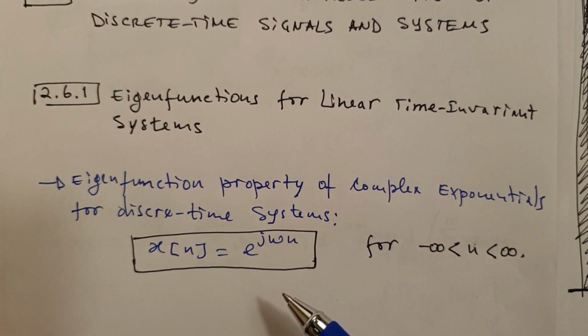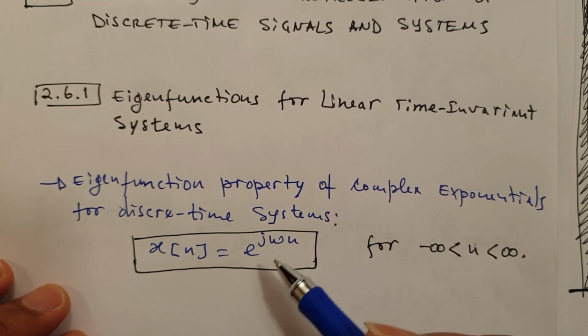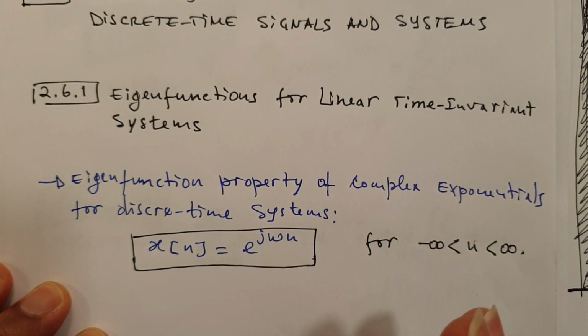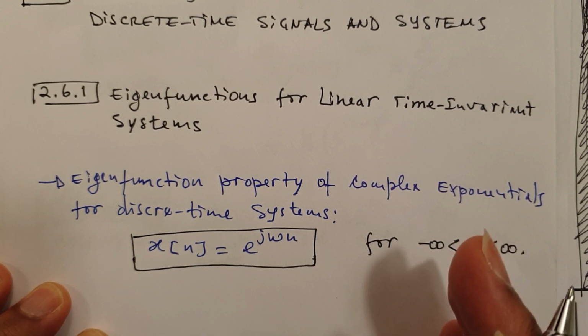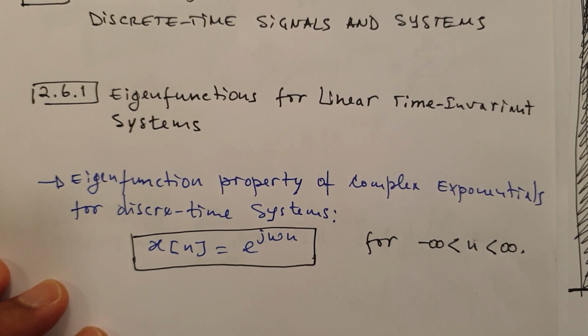As we have seen in the classes, when you multiply anything by a complex number, there are two things that you can achieve. One is that you can scale the value in terms of absolute value, or you can apply a rotation to it. This rotation is the delay. So you can do these two things: scale, which will be like amplify or attenuate, or apply a time shift, a delay.